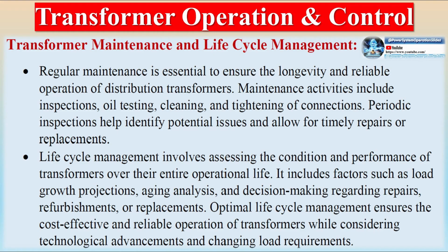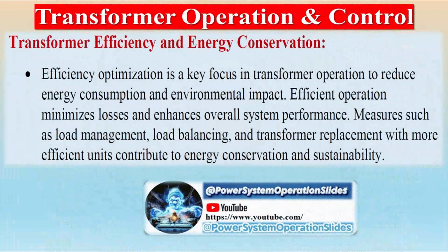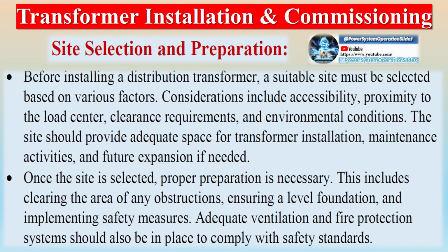Three-phase transformers are employed in industrial and commercial settings, where three-phase electrical power is prevalent. They consist of three sets of windings, each connected to a different phase, enabling efficient three-phase voltage transformation. Autotransformers are a special type of transformer where a portion of the winding serves as both the primary and secondary winding. Autotransformers are used for voltage adjustments, as they provide a variable or tapped output voltage.